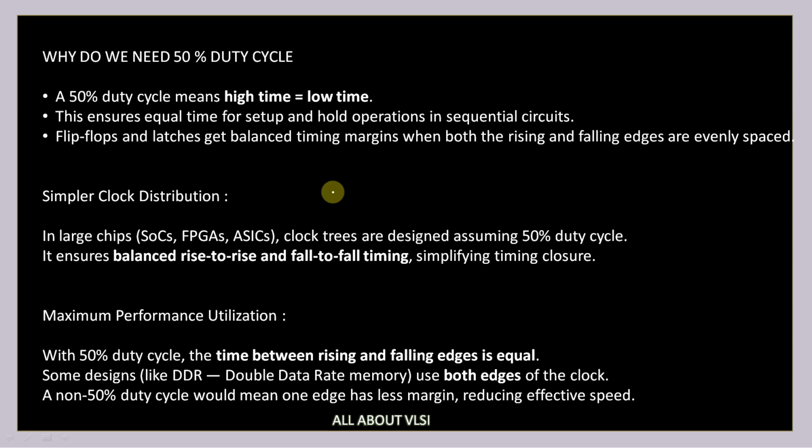If you have a 50% duty cycle, this is going to ensure that your setup time and hold time operations are equal for sequential circuits, and flip-flops and latches get balanced timing margins when both rising and falling edges are evenly spaced. So that's why we need 50% duty cycle. And one more thing is simpler clock distribution. In large chips like SoCs, FPGAs, ASICs, your clock trees are designed assuming 50% duty cycle. So it is going to ensure balanced rise to rise and fall to fall timings, simplifying the timing closure, as well as maximum performance utilization.